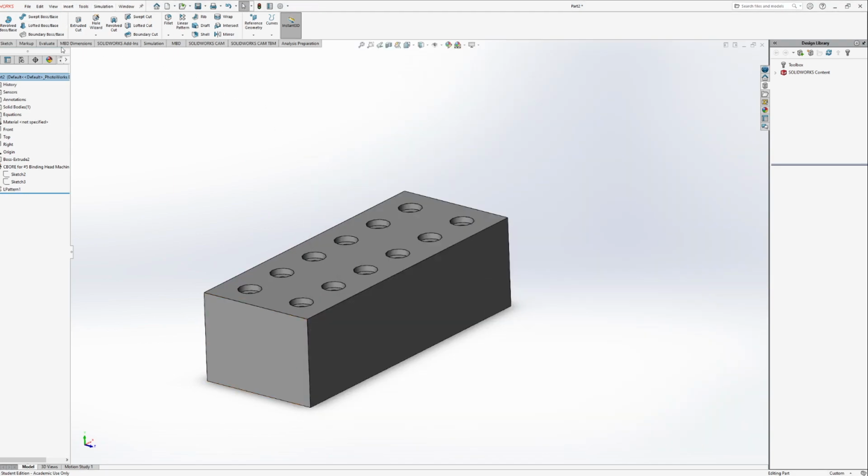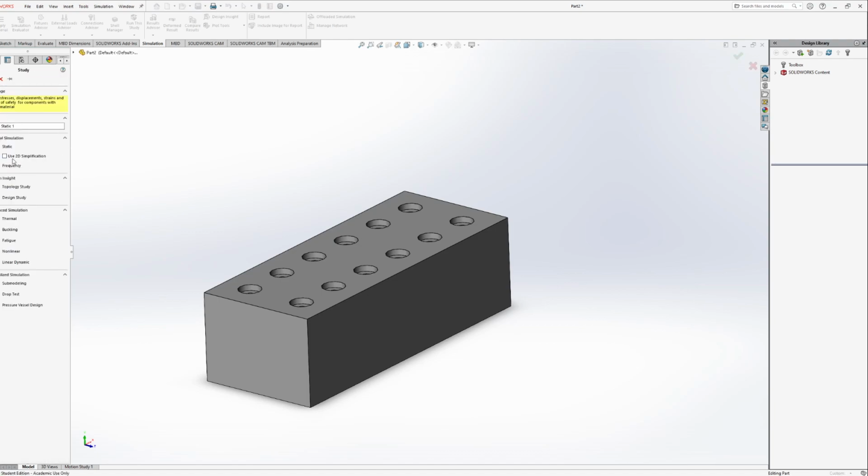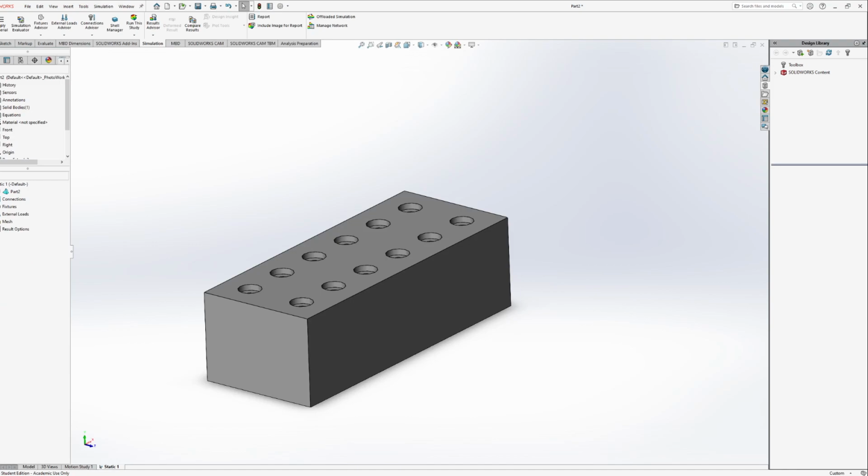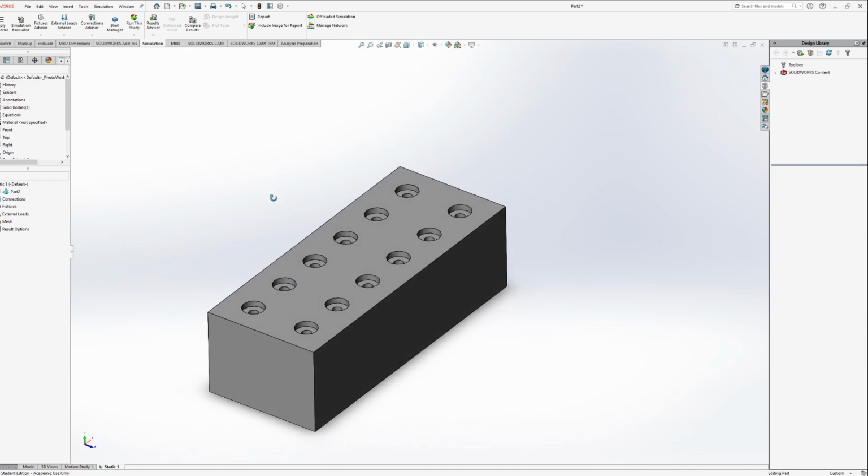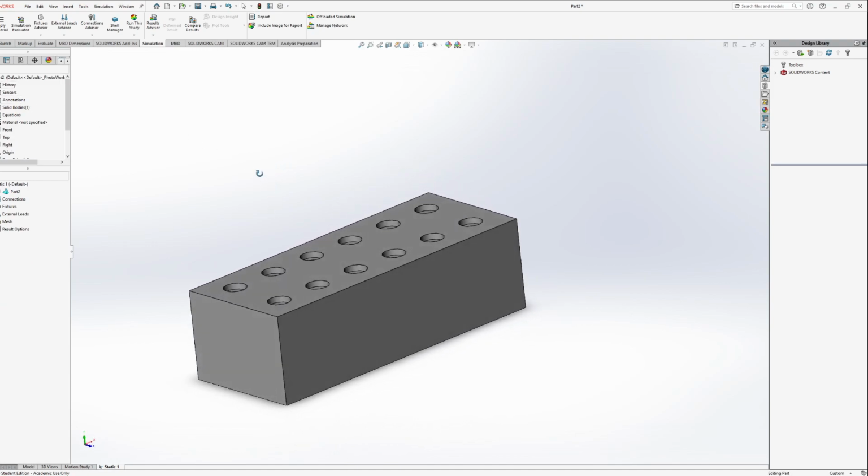if we go back to our SolidWorks, in the command bar, kind of in the middle of it, we should see something that's labeled as simulations. When we click on this, the only option that we're allowed to click is a new study. So we'll select a new study, and we will just start off with a basic static simulation. We're not going to go really into any of these other ones because I haven't really played around with them too much, so I don't know how they function in SolidWorks as well as I do in some other softwares.